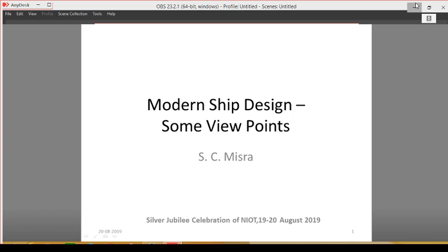Okay, with all those design activities, how do we go about doing it? Perhaps we can talk about CAD modules, generating graphic simulations for shapes, sizes, and distribution of spaces inside the shape, which will go into analysis modules, CFD, FEM, and other software packages for doing various analysis. We are aware of the pre-processing and post-processing for simulation of results, so that one can visualize what will happen when the ship goes into service, and perhaps some decision module where we can utilize MADM or MODM techniques and finally get a solution for various components of the design and the design as a whole. And if the solution is acceptable, go ahead. Otherwise, the design is an iterative process, perhaps it has to be done again.